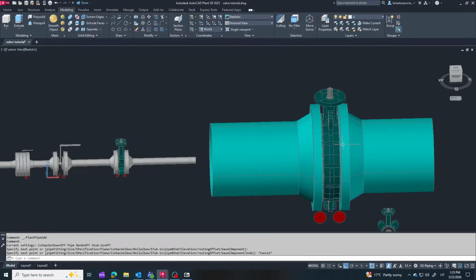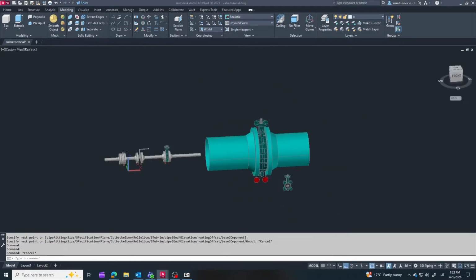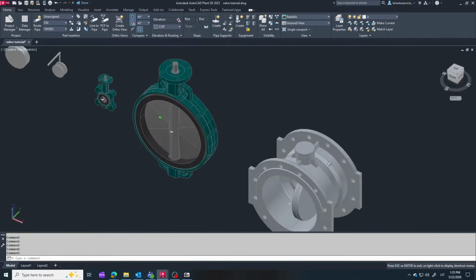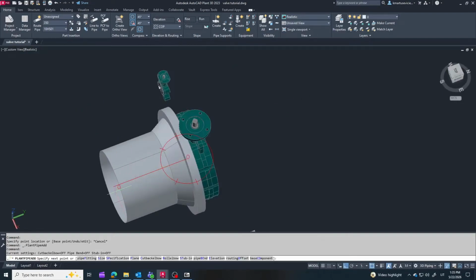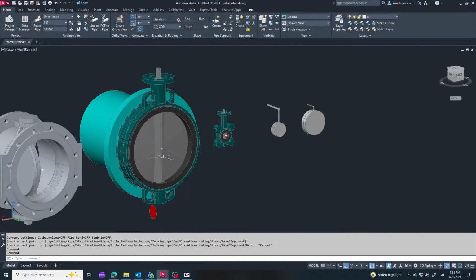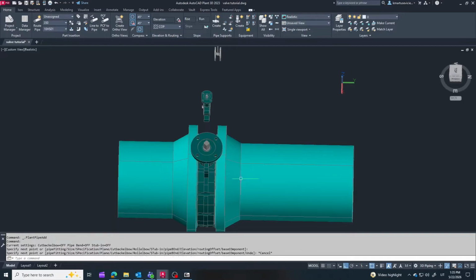One important thing to know is that wafer valves do not have their own full flanges. They rely on the pipeline flanges on both sides for mounting and support. If you need to disconnect one side of the pipeline, once you remove the flange, the valve itself can drop out because it is only clamped between the flanges. That usually means you need to isolate and empty the full pipe section before maintenance. This is one reason why lug-type valves are sometimes preferred in systems where one side may need to be disconnected separately.